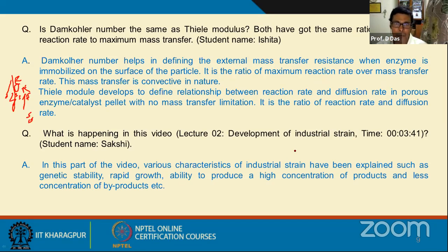So suppose I worked with a citric acid industry, the capacity of our production fermenter was 200 cubic meter. So 5 to 10% is what? It is 10 to 20 cubic meter. So our inoculum vessel's capacity was 14 cubic meter, that is 14,000 liters. You cannot produce that culture in the lab, so you have to produce it in the plant. In the lab, you prepare the seed culture, transfer it aseptically to the inoculum vessel and produce the culture, and then aseptically transfer it to the production vessel.